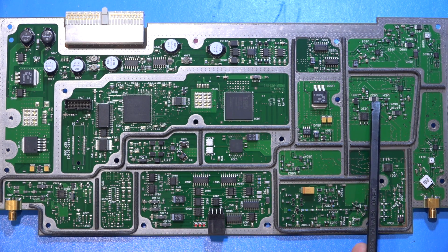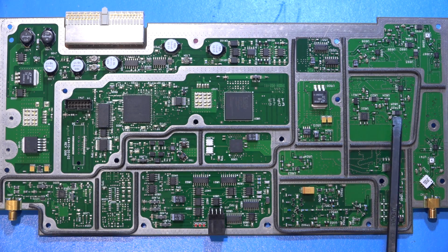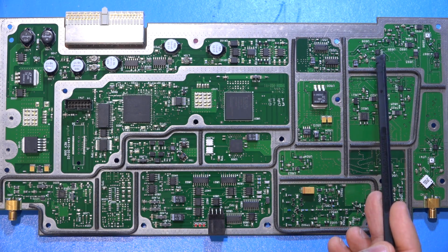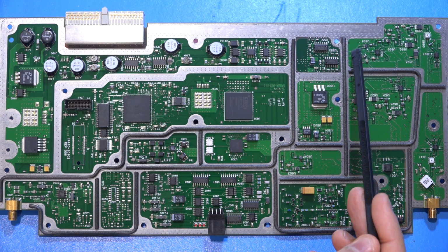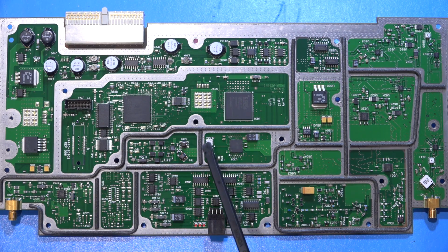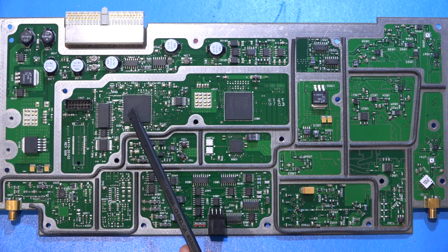After this, we have another doubler. That's a Hittite part. And then we have another amplifier. Sorry, this is an attenuator. So doubler, programmable attenuator, into another selector switch, split into 3 again, and they come back into this one. Right over here, we have then 2 paths. One path is fed over here, through amplifier stages, and then onto the mystery chip. The same mystery chip that we saw earlier on the other side, or I haven't shown it to you actually. That's a programmable divider again, going into some output filters to clean it up, and that goes back onto the FPGA.